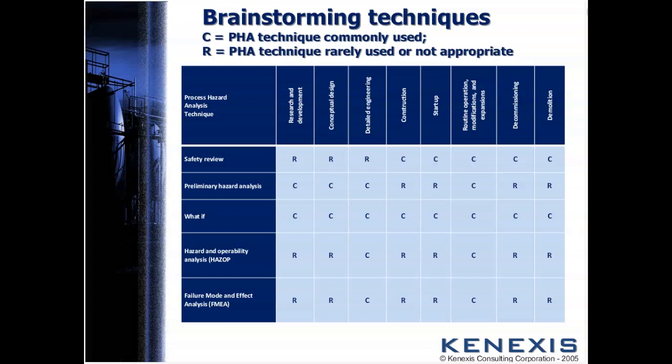Now, we'll talk more about the applicability of the various techniques in a minute, but I wanted to show you how they're distributed over the typical life cycle of a plant. If you look at the safety review, which you've been reviewing for a minute or so here, it's not used very early in the plant. You don't have a lot of anything on paper, so it's hard to just brainstorm a conceptual design. But it's used a lot in the later phases of the plant, everywhere from construction cleanup to demolition.